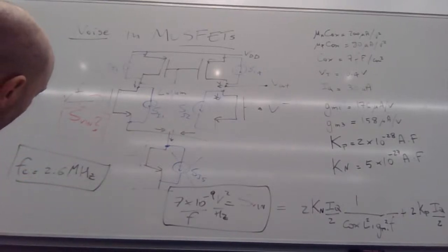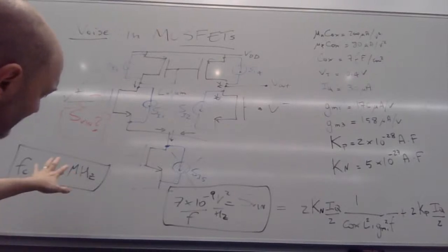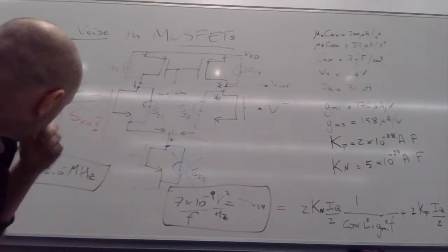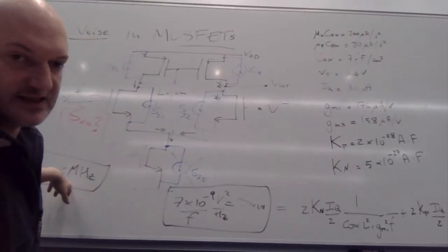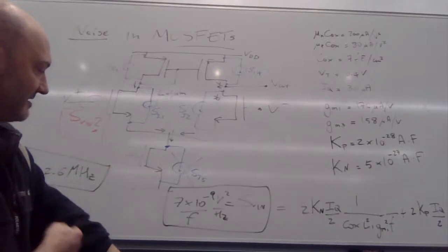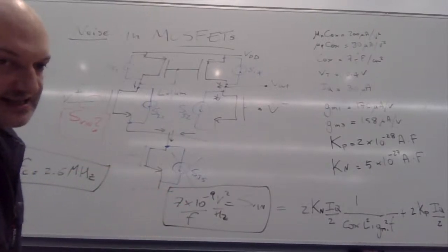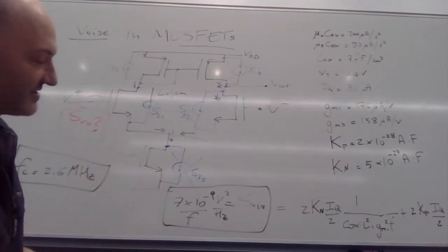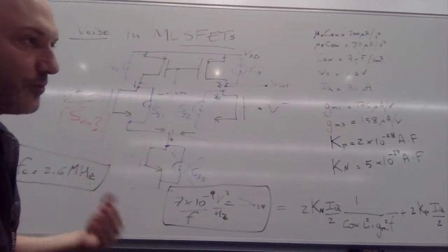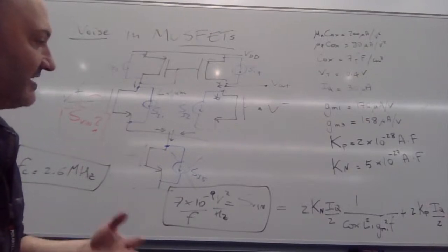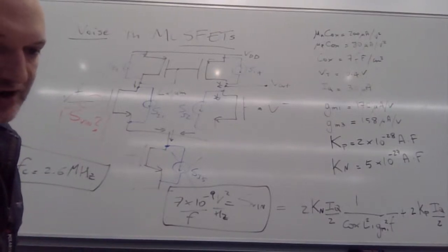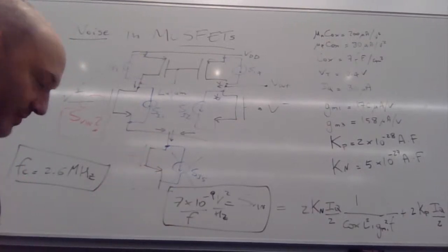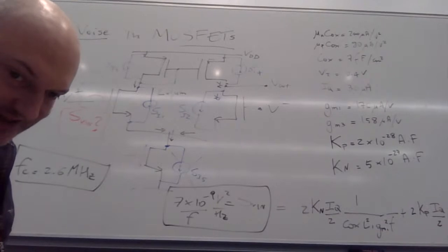Now, datasheets vary on how they report these things. Sometimes they state the corner frequency, sometimes they state the actual spectrum, sometimes they state the RMS value of your noise in a frequency band. So they say between 1 Hz and 100 Hz, the RMS value of your noise is, I don't know, so you need to be careful on how these things are accounted for.